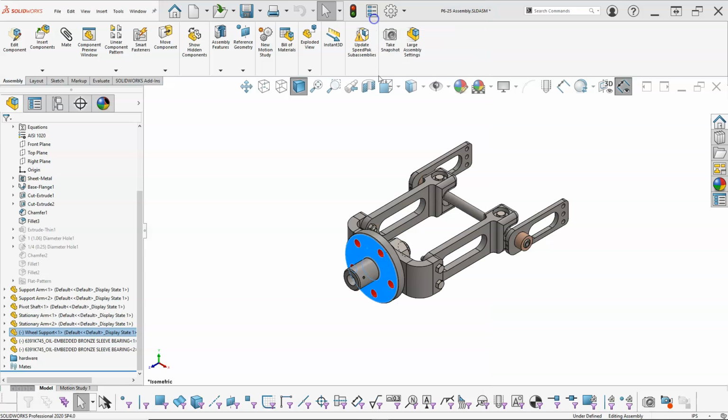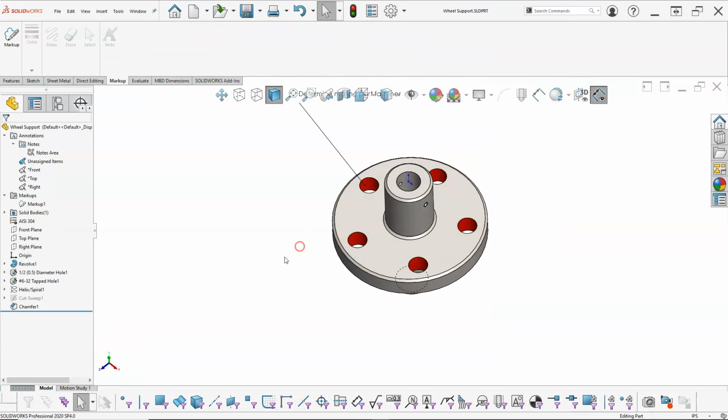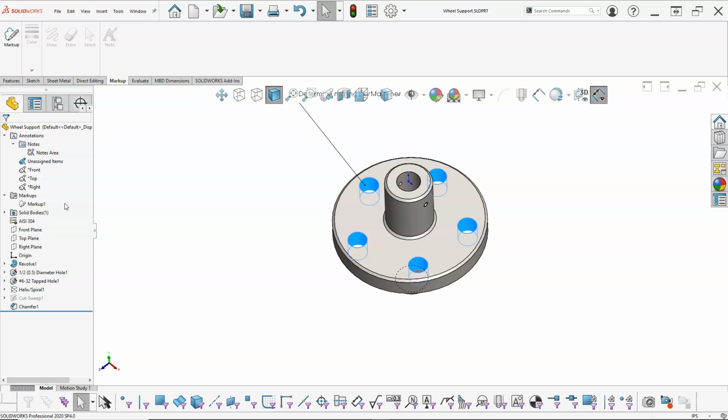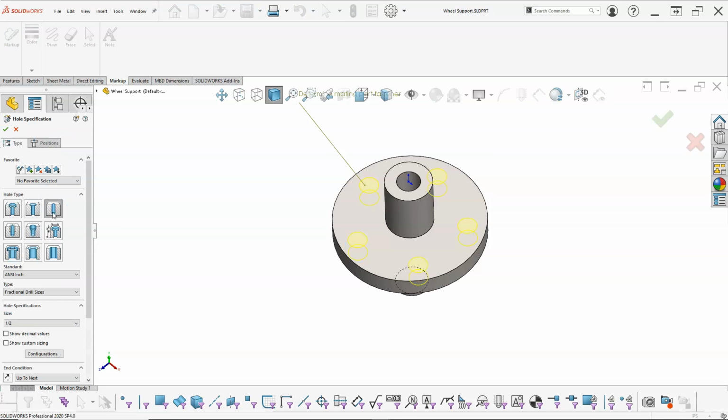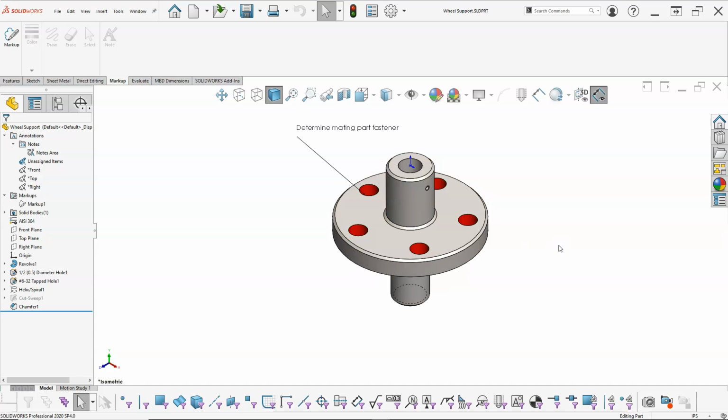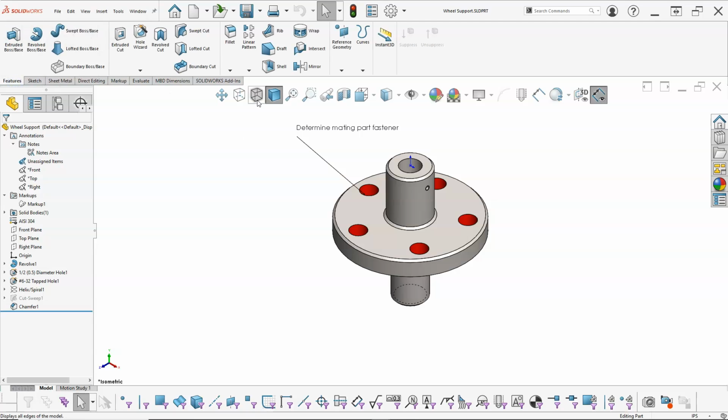In which case, if I open that back up, it's already open. I can switch it that way. We come over to the ½ inch. The nice thing about the hole wizard is that when I edit that feature, I can switch it to a threaded hole, pick the ½ or, as big as this is, the 1"-8. You're able to carry a lot of weight, but this hub is pretty small for the point-to-point base circle, so I don't know that we would need as much